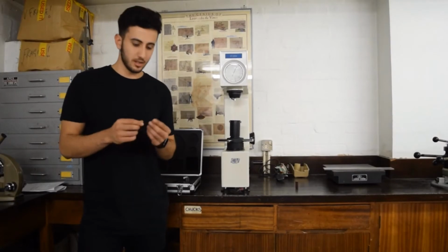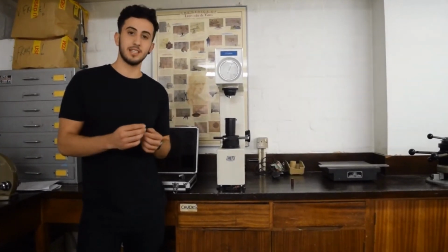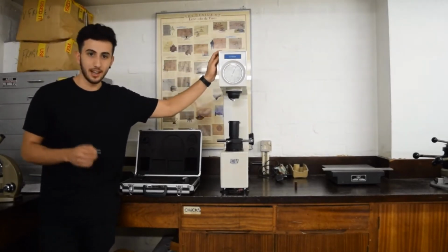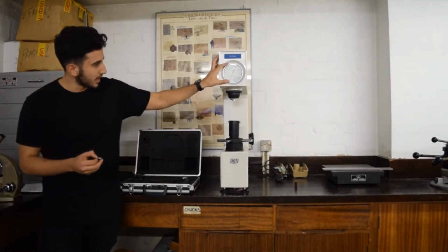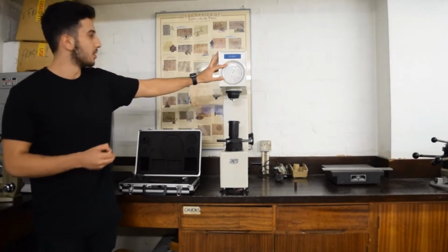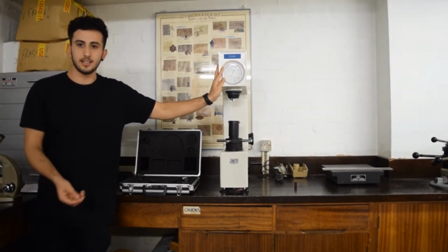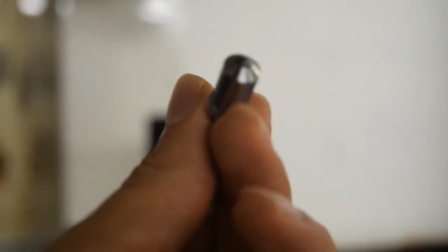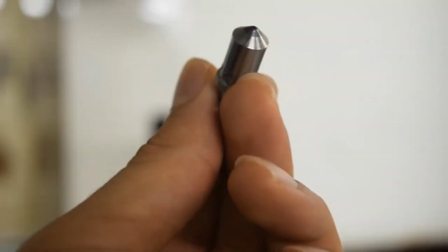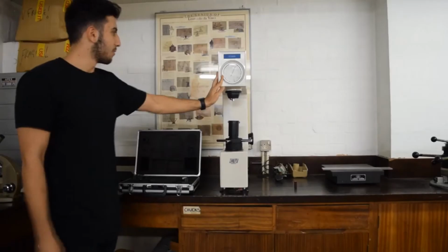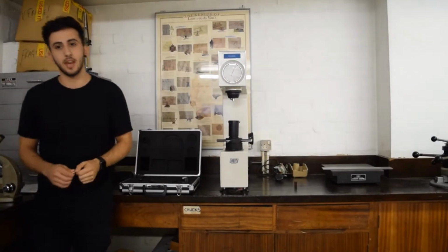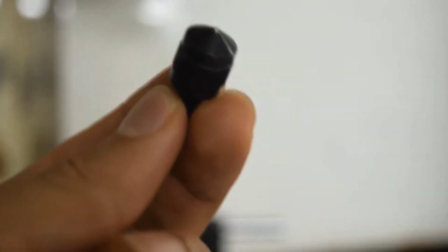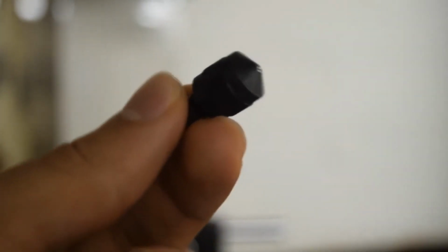Hardness test is used to test the hardness of a material by indentation. This machine here is a CV600A, which is a hardness tester, and it's got two scales, scale C and scale B modes. Scale C uses a diamond indenter like this one. It measures materials like quench steel, tempered steel, more of the harder materials. Whereas scale B measures aluminium, alloys, copper, malleable cast irons, but that one uses a steel ball indenter.